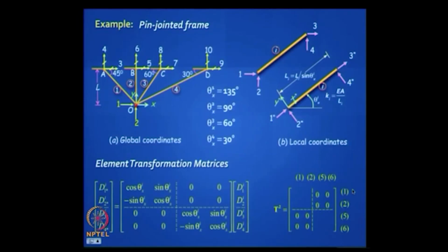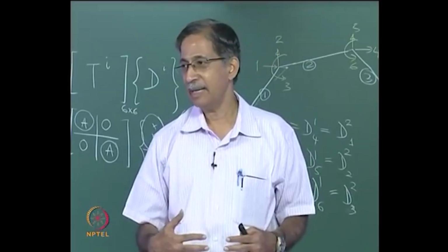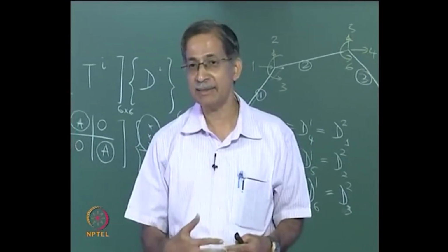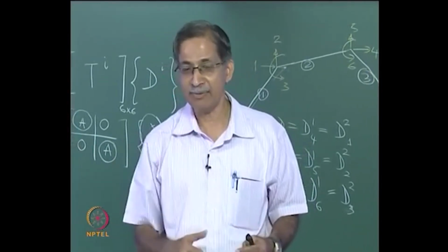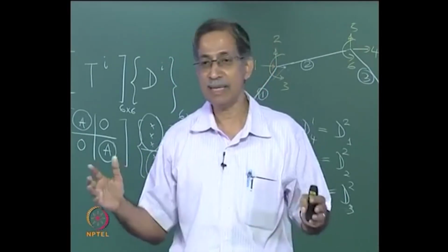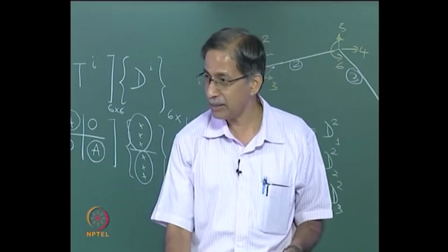This is a clue for me that the displacements that I get at the element level are the same as the displacements I get at the global. No plus here, be careful, it is exactly equal. So it helps me assemble my structure stiffness matrix from my element stiffness. Is this picture clear to you?